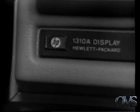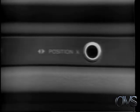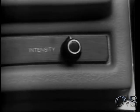Electrically, the 1310 and 1311 are identical, differing only in CRT size and front panel control locations. The 1310 has a 19-inch CRT with front panel controls across the bottom for focus, astigmatism, position X, position Y, power on indicator, and intensity. The 1311 has a 14-inch CRT with the same controls mounted vertically along the right side.